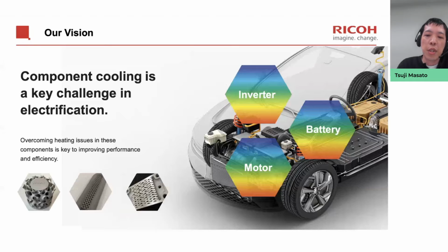Compared to the existing metal 3D printing method, such as SLM, binder jetting can offer higher productivity and is more suited for mass production. Aluminum alloys are extremely difficult materials to sinter, the final step in the binder jetting process, but we are working to address the issues with a unique sintering method.